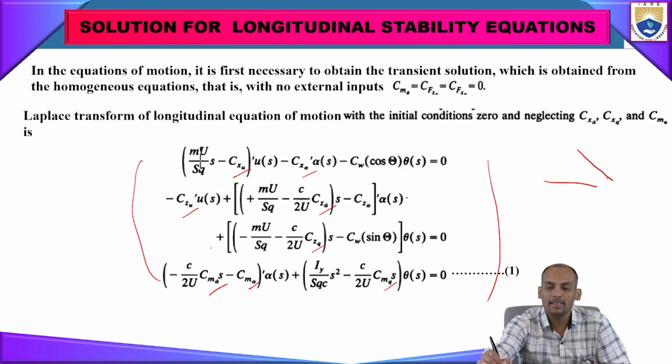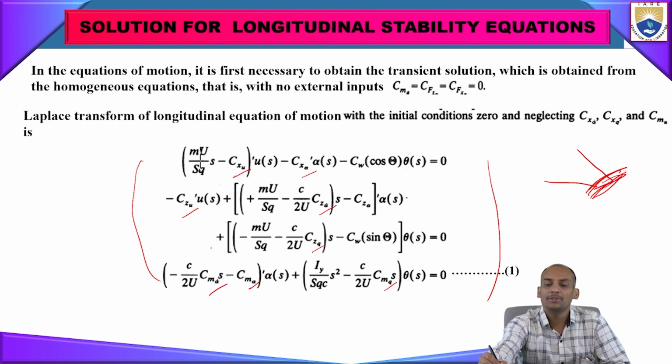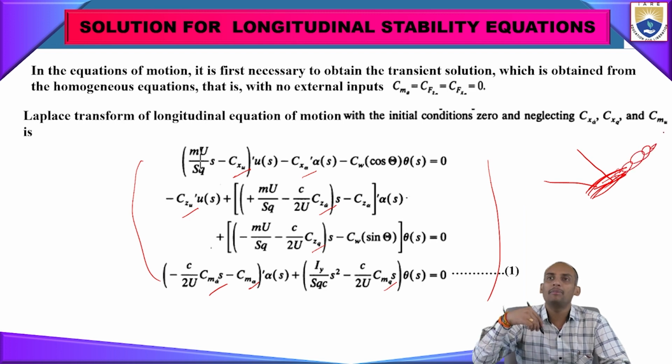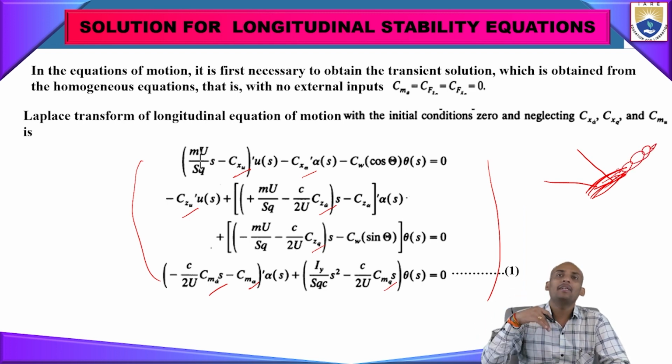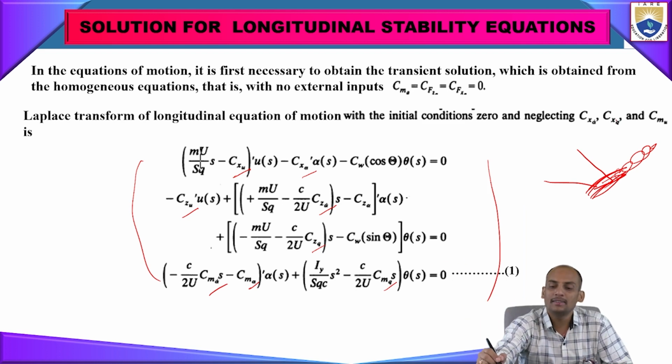Here we get high pressure and low pressure mixing up. The aircraft will experience low pressure and high pressure mixing velocities near the tips. Due to that mixing of velocities, the vortices will be formed. Due to those vortices, adverse pressure differences will occur, and they will continue to the tail also. Here the tail is there. So the wingtip vortices will continue till the tail.